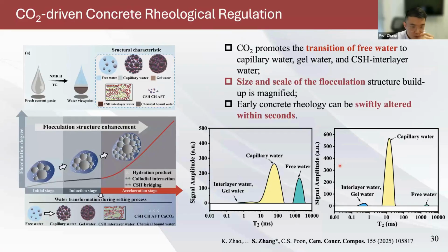Some mechanism: we try to review the mechanism behind the CO2 interaction with concrete. From a rheological perspective, we found that CO2 promotes the transition of water status. It significantly promotes the transition of free water into capillary water, gel water, and C-S-H interlayer water, and forms a larger flocculation structure. How concrete changes from a liquid phase into a solid phase, all the magic starts with the flocculation structure.